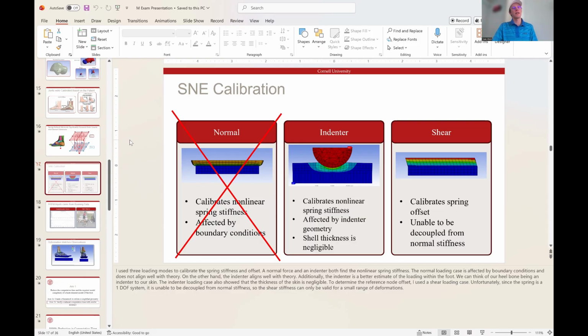I'm only modeling it as simply a spring, so tendons are just linear elastic, but you can start adding in damping terms to show more viscoelasticity in the tendons over time. But I just assume since the stance phase is so quick, I can model it simply as an elastic element. But yes, to answer your question, there are parameters that you can tune, especially if age is a big one too.